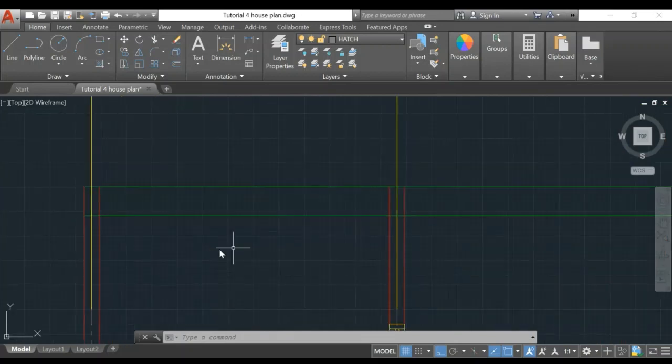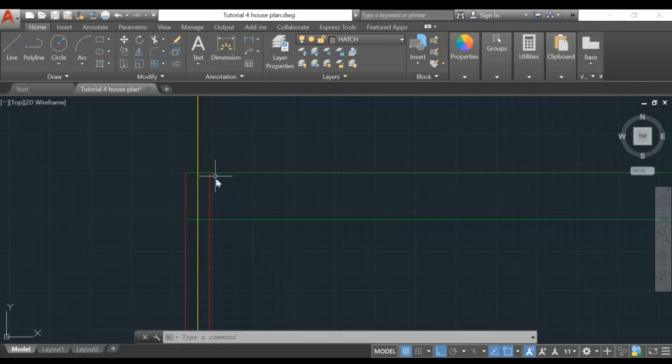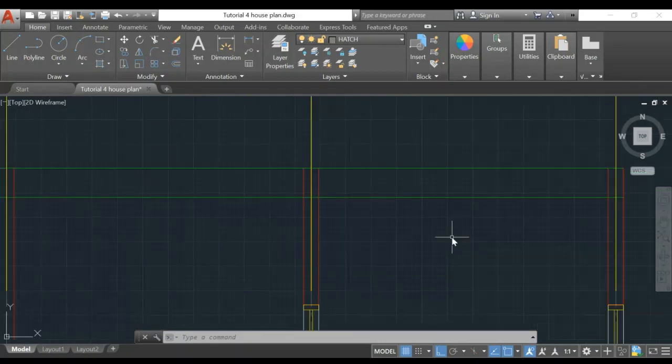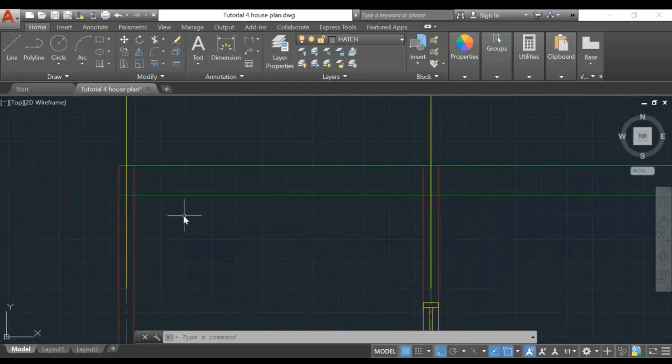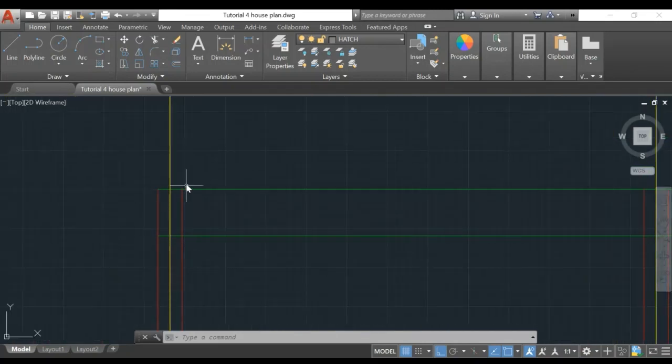So there are a few ways of doing the beam as well. Some beams nowadays are made almost the same as the walls, with a thickness of 150, so that you don't see the beam. If the thickness is constant inside the wall, it means the depth of the beam should be bigger. But I'm going to do the traditional building, where the beam is 100 by 200 mm.